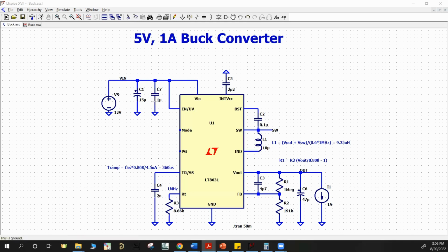And this particular capacitor, as we're going to discuss in the next video for the layout design, must be placed very close to the VIN pin. The reason for that is because this smaller capacitance's sole role is to filter out all the higher frequency noise that may be present on the VIN bus. So always ensure that the lower capacitance values are closest to the input pin, because they are responsible for filtering out higher frequency noise before all that high frequency energy enters the chip.